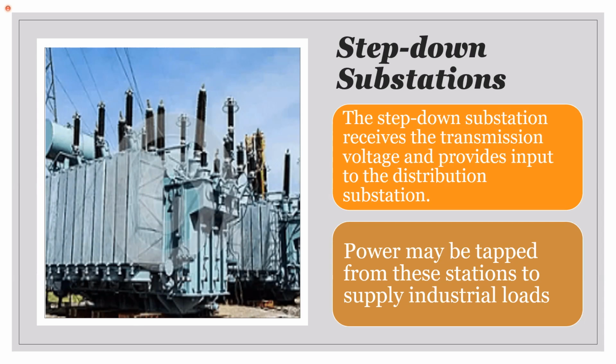So it's taking it from the high transmission to a lower, or if you want to call it a subtransmission voltage. Because of the fact that our voltages are so low, which is what I said earlier, it is really not the done thing, but in terms of the input to our distribution substations, their input is primarily 69 kV.